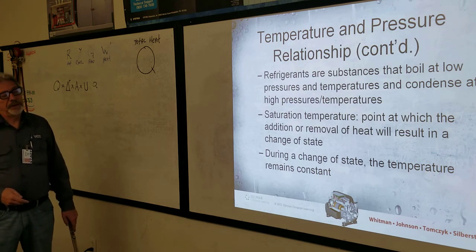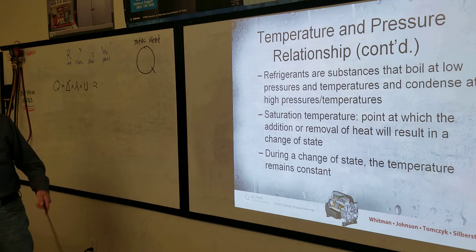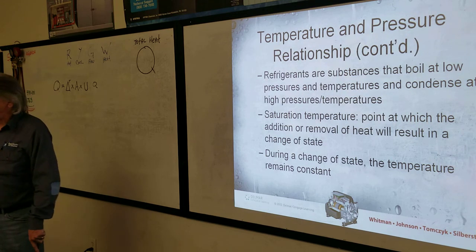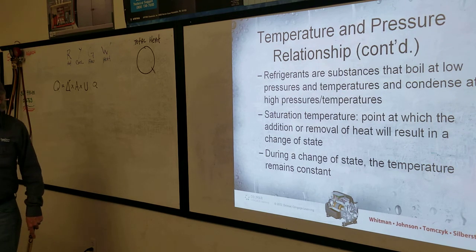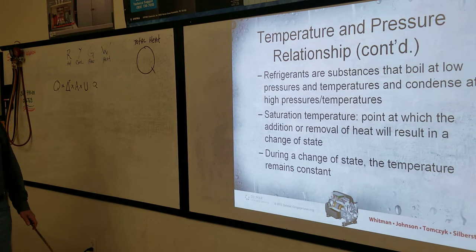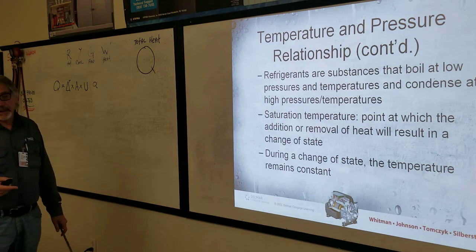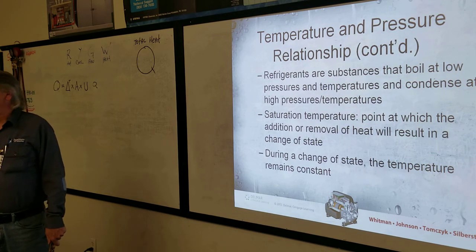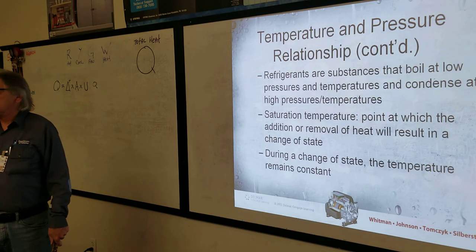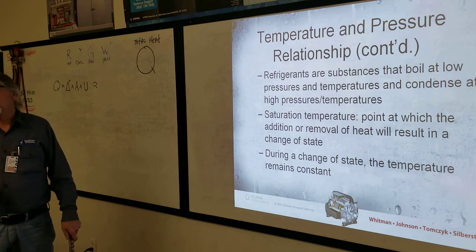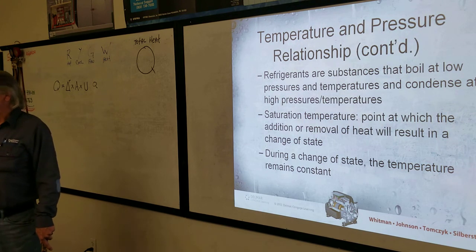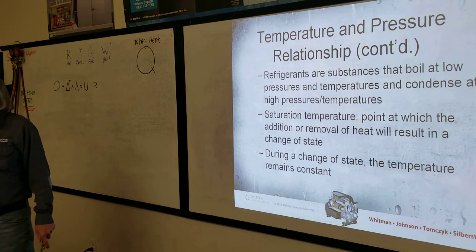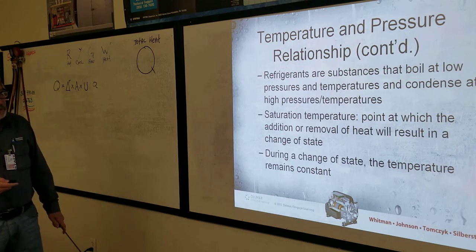Okay, so we're talking about change of state, just like water changes from a liquid to a vapor. And we talked about that, right? Where it actually absorbs heat. A pound of water at 212 degrees that absorbs 970 BTUs of latent heat is now steam. Okay?